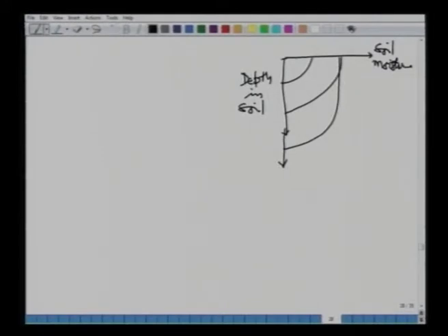If you look here, there are three curves. For this first curve, the moisture content is less than the maximum, which is, let us say, eta is the maximum. So, obviously, on this curve the time is less than Tp, because right at the ponding you have saturated conditions close to the ground. Just when the ponding has occurred, that is t is equal to Tp, then on the ground you have saturated conditions, and as you go down the soil moisture reduces.